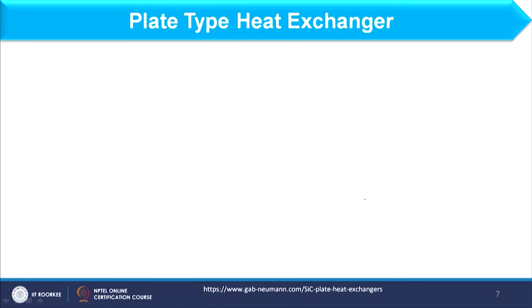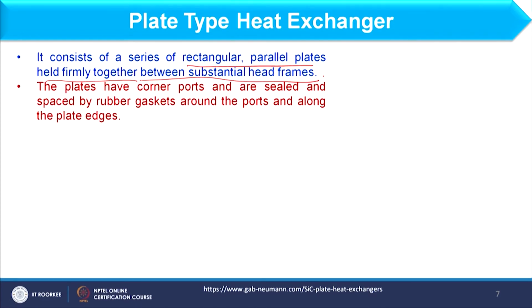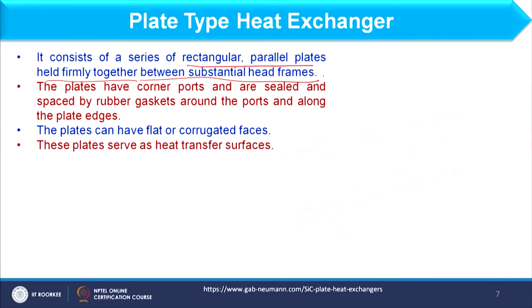Now let me focus on plate type heat exchangers. Okay. As we have tube and shell in shell and tube heat exchangers, here we are dealing with plates. Okay. So it consists of a series of rectangular parallel plates held firmly together between a substantial head frame. So here you see in plate type heat exchanger we have the head frame, that I will show. Okay. Let me show that first.